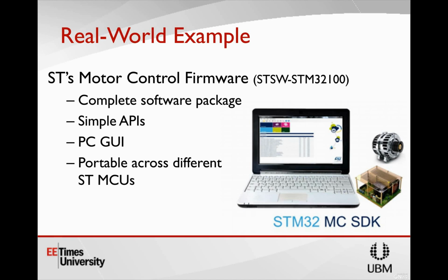So those are the two biggest drawbacks of sensorless: the low speed range and no position control. And then obviously the biggest drawback of sensored is that you have a sensor. It can be costly from a layout perspective because now you have additional power supplies you may need, additional wires, additional connectors, and it's also a system robustness problem because that's the part of your system that's most likely to fail, and if it does fail, it causes a lot of problems because now your motor just won't work.